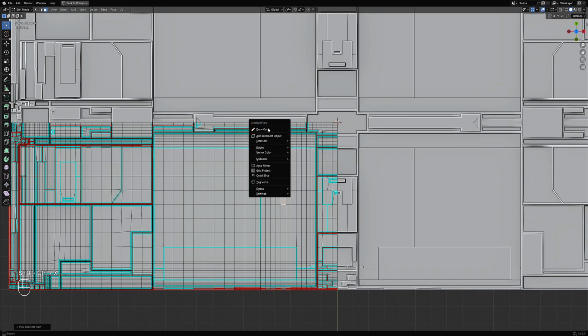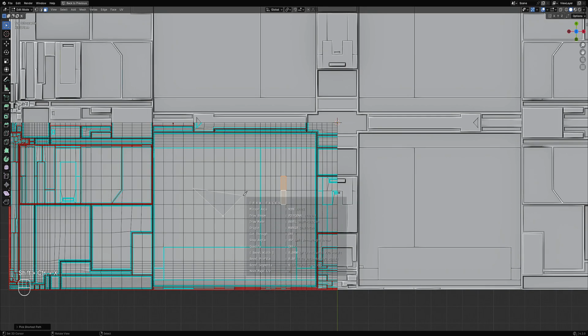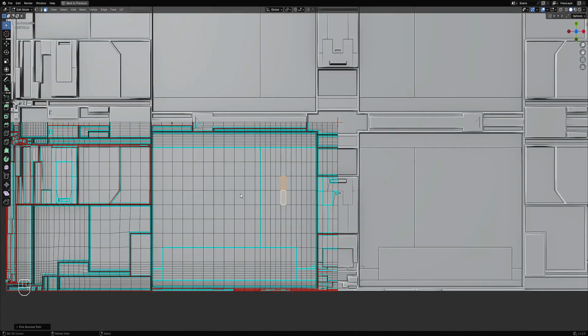If you have tools like the creative flow and draw cuts, then creating details on ngons is much easier. But if you don't have this tool, then the quad topology is helpful for you. So maintain the quad topology as long as you have plans to manually model in some details.